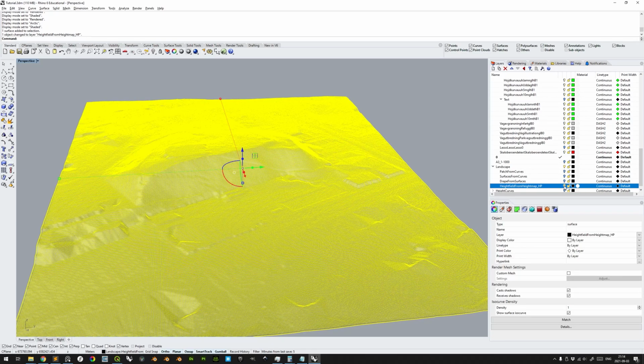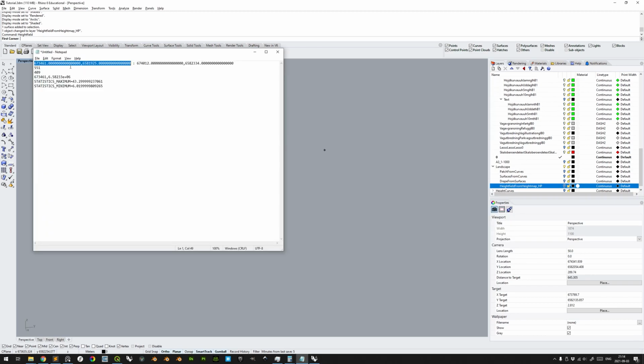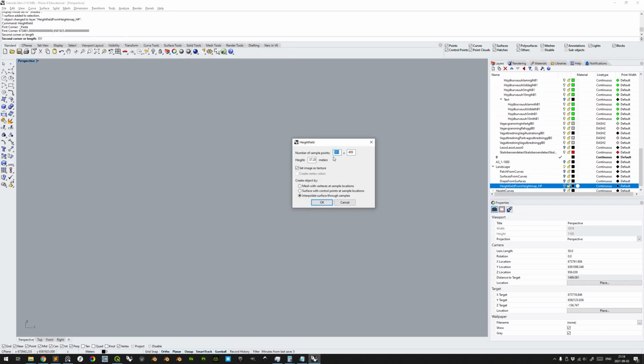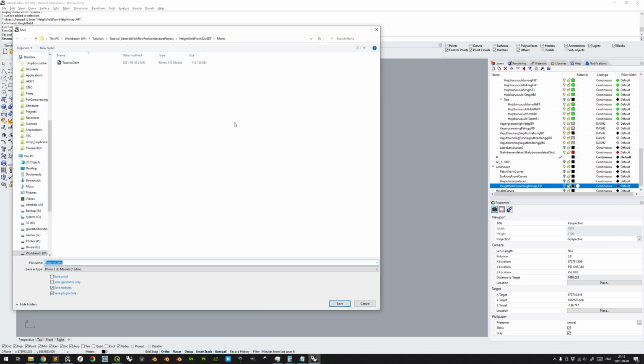we can hide it. We'll redo the Heightfield command, use the same image texture, and for the first corner we take the minimum extents coordinates again, and for the second corner, or actually the length, we input 551 and click to confirm, and perhaps we can choose roughly half of this, so perhaps 275 and 205. Click OK to confirm, and we can save before running it.